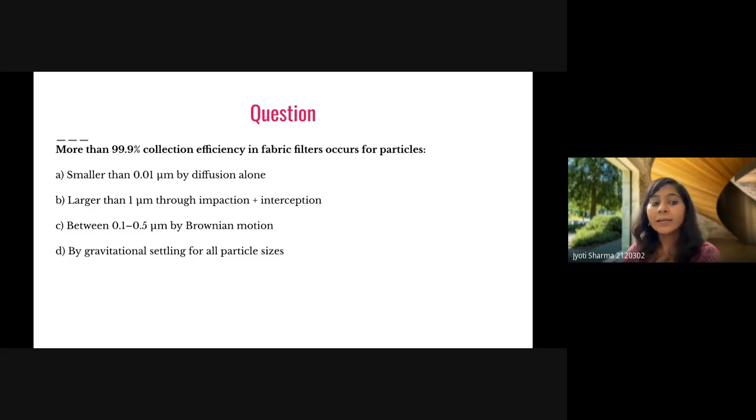Whenever we increase the particle size, obviously the efficiency will increase. So whenever we have impaction plus interception and the size is larger than 1 micrometer, the efficiency will be very high.